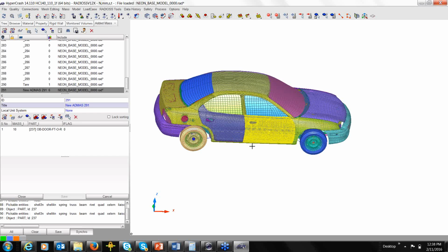Nowadays we can see a full vehicle model at 5 million elements, and we tend to shoot for over about 10 million elements, because what the industry is leading towards is to have one common model for all the vehicle impact modes, meaning durability, NVH, and then crash.